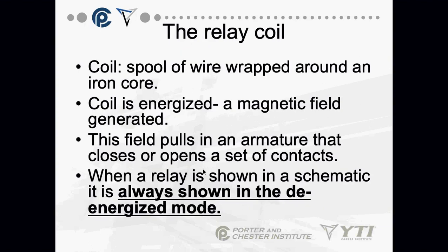So the relay coil is a spool of wire wrapped around an iron core. Why do I care that it's wrapped around an iron core? What's so special about that iron core? It's highly conductive and magnetic. It helps create that magnetism. If I energize a coil of wire around an iron core, or any piece of metal, quite honestly,